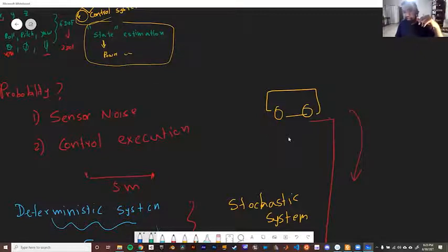If you have something like the Kalman filter, it will tell you the robot is somewhere here, but it will not only tell you where it is most probably going to be, it will also give you a certain uncertainty. It will say the robot is most probably here, but given the uncertainty, it could be in this area. It's like when we give a reading and say plus minus whatever. That way, the robot can make more intelligent decisions.